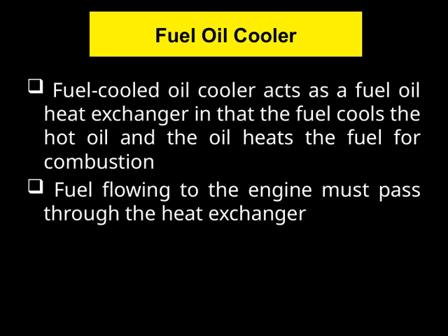It's important to remember that the fuel that flows to the engine must pass through this heat exchanger first. This step ensures that the fuel is at the right temperature for combustion, preventing issues like fuel freezing or overheating. So, in summary, the fuel oil cooler plays a dual role. It cools the oil to prevent overheating and preheats the fuel to ensure smooth engine operation. This interconnected system is critical for engine performance and reliability, fitting into the bigger picture of efficient engine cooling and fuel management.